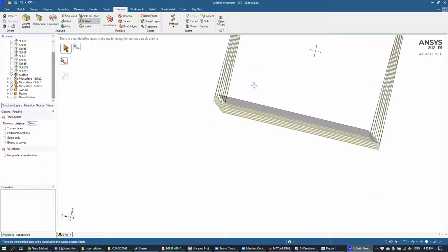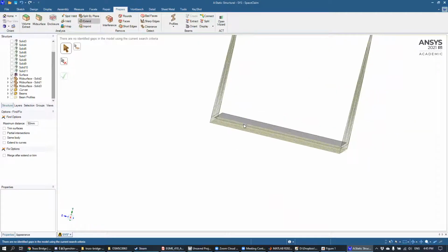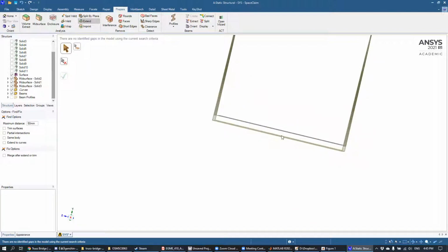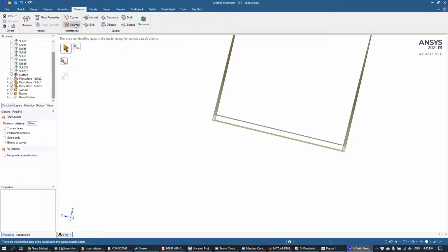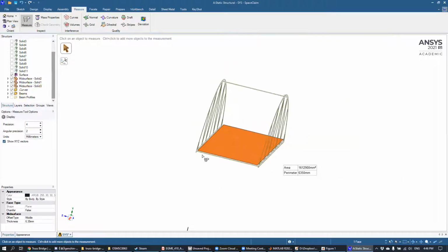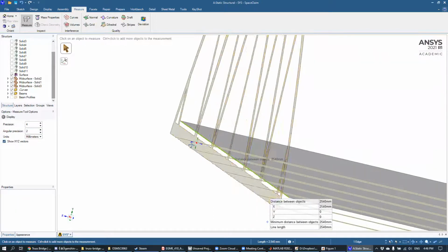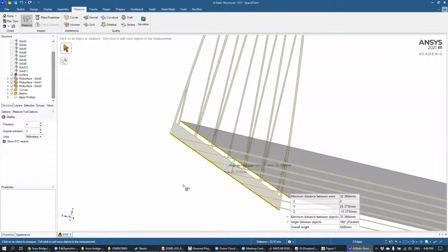Instead of moving it up, you can see here that the road needs to be pushed downwards, right? Because ideally the road should be resting right on top of the columns, because the columns on the bottom are supposed to be giving that road support. So we need to move this road down. But once again, we need to measure how much the road needs to move down. So we're going to click measure here. Let's find the distance. Actually, we need to find the distance from the edge of the road down to the bottom edge of the bridge.